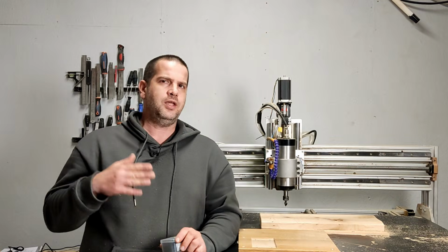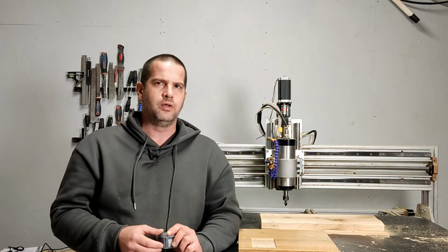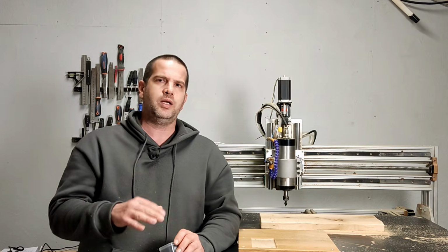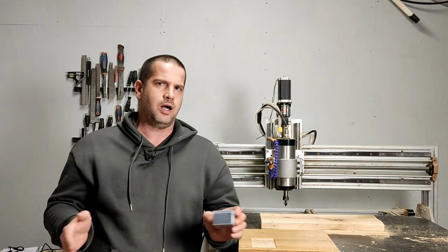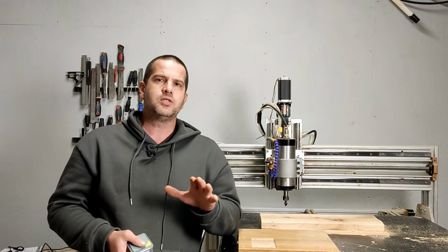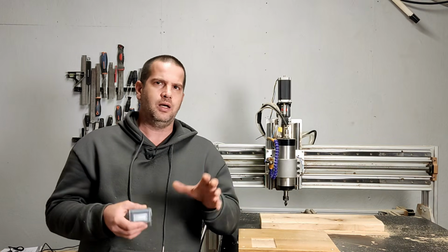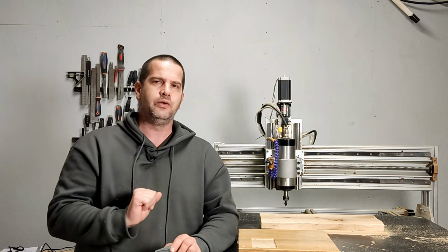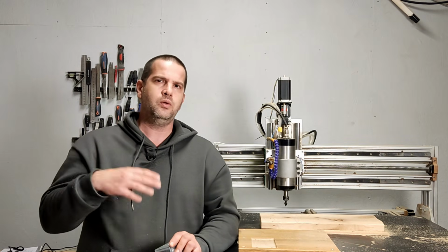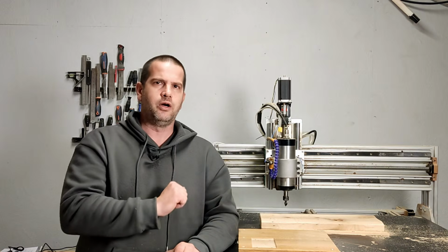Let me tell you why I think that the probe is really useful. It is useful especially when engraving things and when using the V-curve operations, because if the material isn't perfectly flat, the lines won't be as they should. So probing the material and getting the exact shape that the material has is a great addition to any CNC, especially smaller home-built CNCs that don't have perfectly flat surfaces. So let's go to the computer and start today's episode.